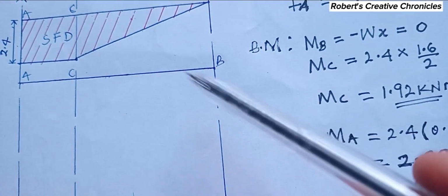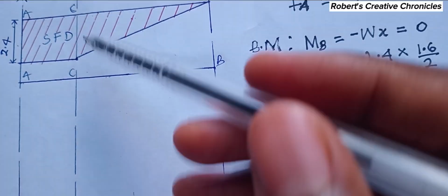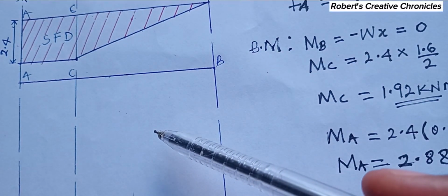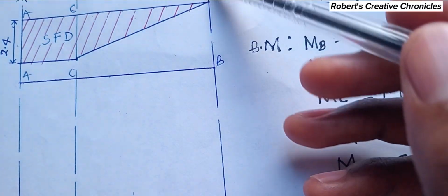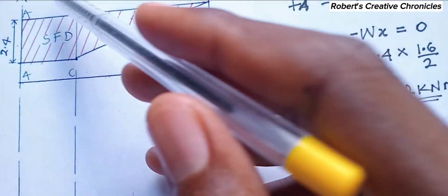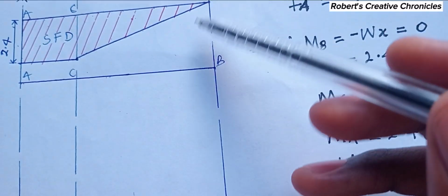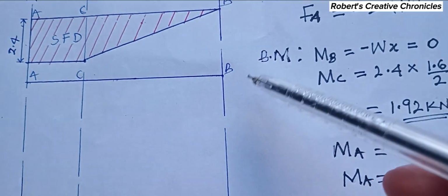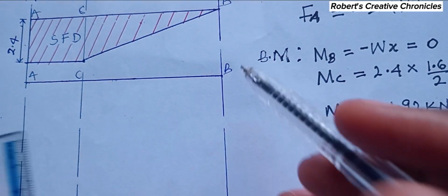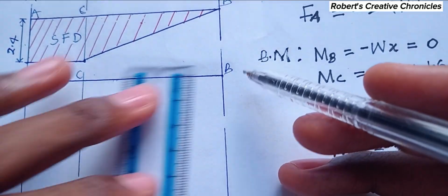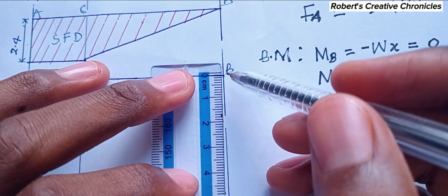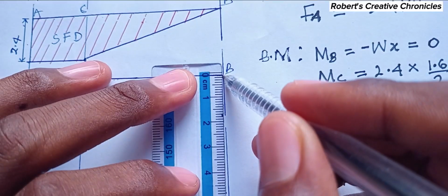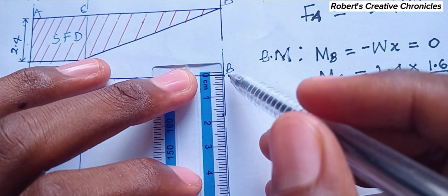In this one, any force acting downward, I take as negative. Any acting upward is positive. When we do simply supported beams, the forces are going upward, so we'll take them as positive. But in this one, they are coming down, so I'm using the lower part of the axis of the Cartesian graph.